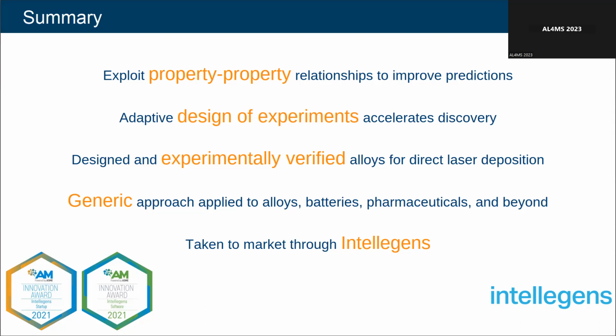Now, about first principles methods, they are important for us. In the first project, we were using a method called CALPHAD very heavily. That's one that predicts the thermodynamics of alloys, which phases are going to form in them. We first performed about 150,000 CALPHAD calculations for our database so that our tool could have a really good understanding of all of these pesky phase transitions. That was regarded as one of our input properties, just like weldability, which we could then correlate to the strength properties of the alloy. And so we were guided by those first principles calculations.